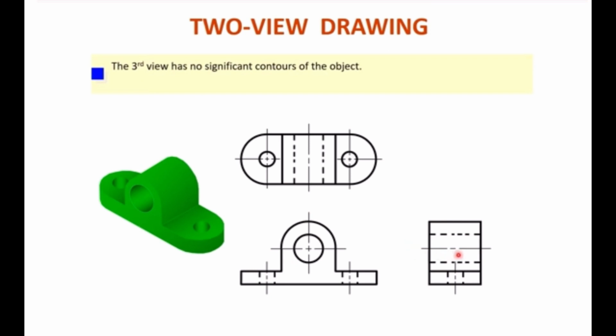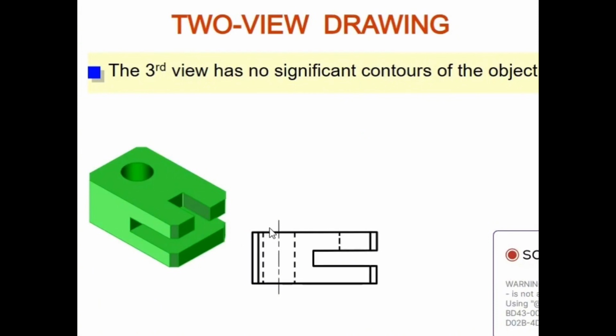That is the symbolic representation of center line. So when you see from the top, these circles and the bigger circle will be hidden. So now that is unnecessary. Why? You will get the length of this object. So the length of the object is like a curve. There are 2 holes present at the bigger hole. All the dimensions you can mention clearly on these 2 figures, so this view is unnecessary.